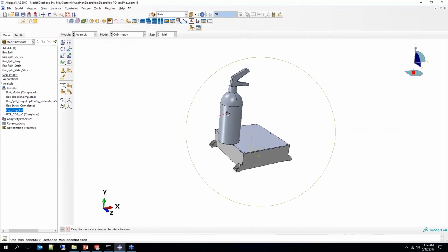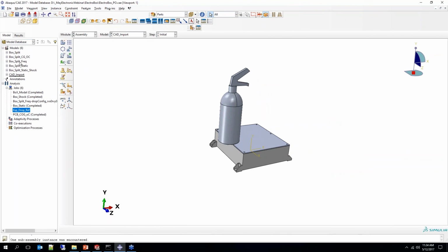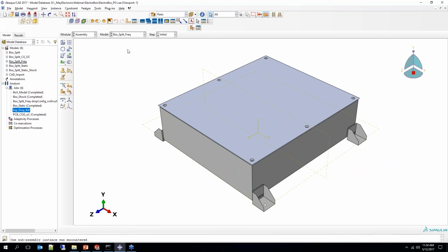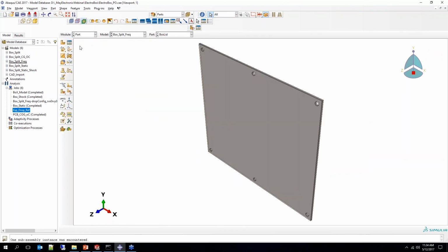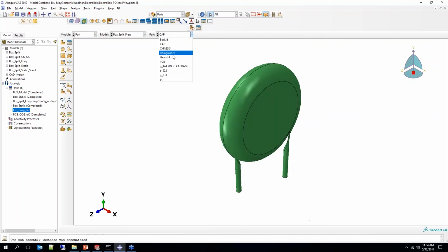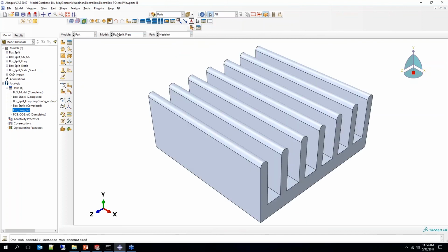So the workflow in Abaqus is dictated by the module that you're in. So you'll drop down through the modules and complete them as you go. I just pulled in some aluminum material data from SOLIDWORKS. We have a few choices around failure mechanisms: damage for ductile metals, or we have brittle cracking and other options if we're in glass or in concrete.